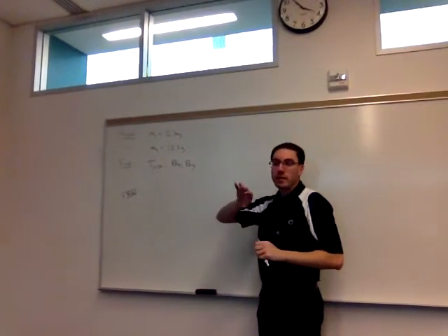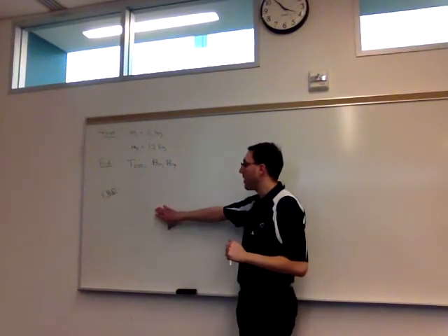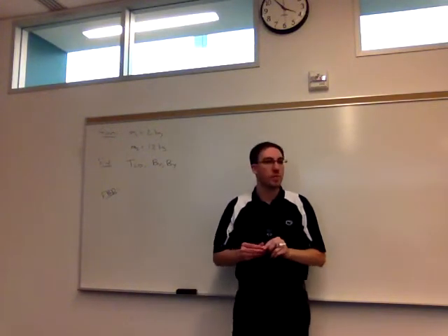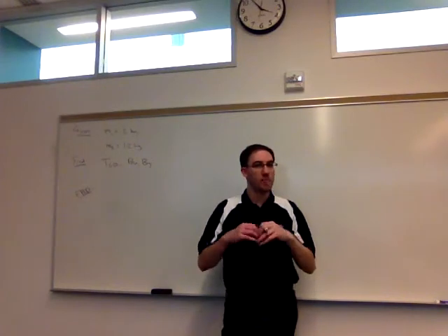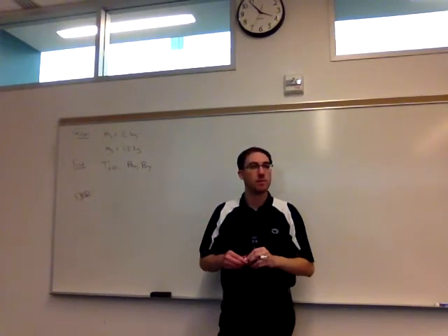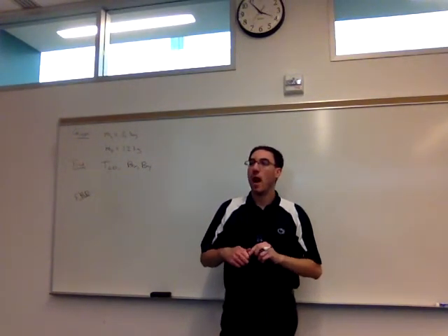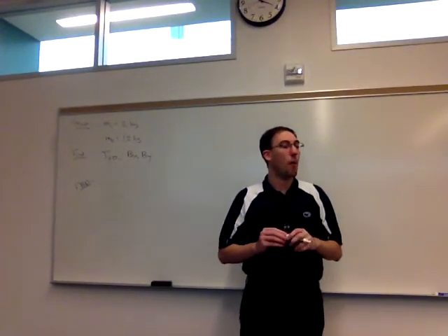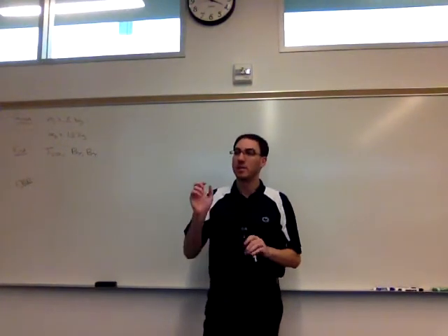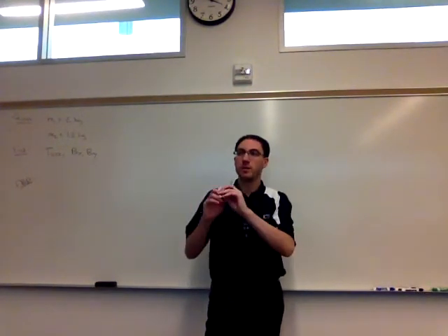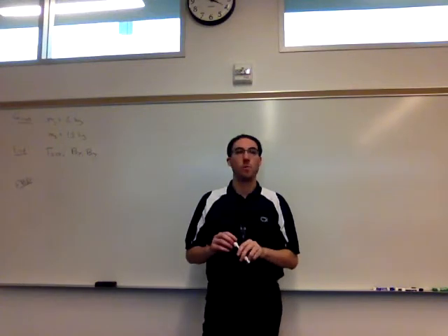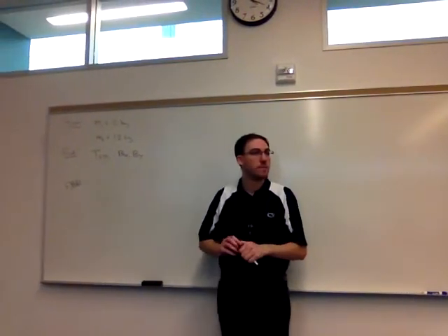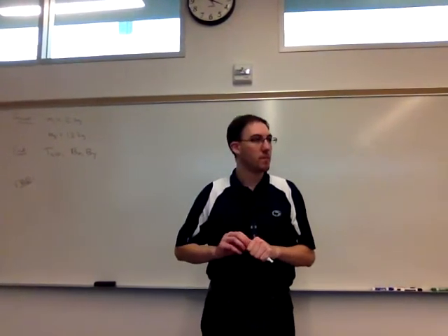Right, so using the structural analog, we want to draw the free body diagram of our system. So before we draw anything, we want to select what's going to be the object of interest that we're isolating from all of its connections in this problem. Well, it's a rigid body, so it's not a point that we're going to be isolating. The beam. Yes. So do we want the beam, or the beam and the cord? Both would be okay. Both we could draw a free body diagram of.